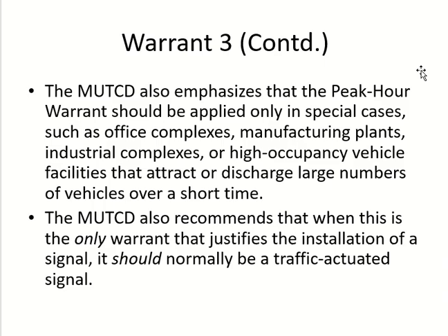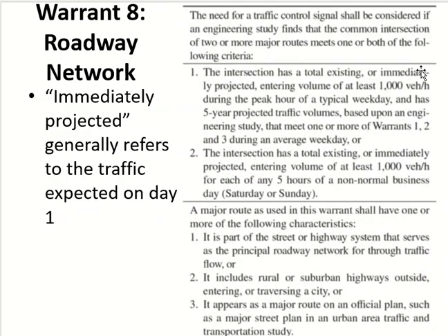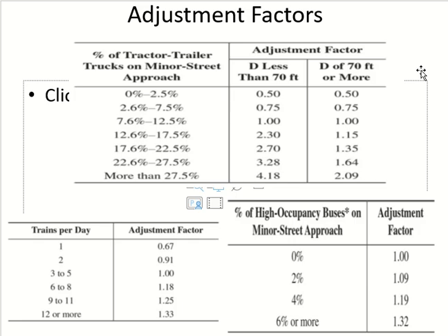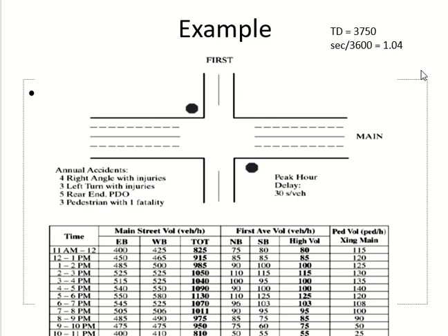Okay. If you look at the peak hour, so we are talking about this hour, right? So minor should be more than 100, it is, and the major should be more than 800. So if the delay was not a problem, this would have been met. Okay, if you have got the delay 4 hours or more, this condition would have been met. But right now, not met.